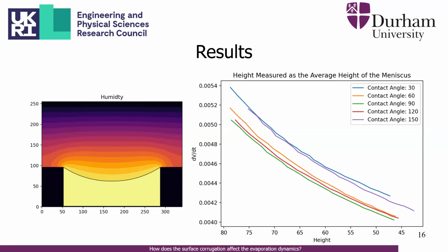So how do you define the location of the liquid gas interface? Because it's a diffuse interface, right? I'm a bit confused about how to do the interpolation. The distance is based on just assuming a tangent profile, for the halfway point at 0.5 in the profile. Because we have a diffuse interface, we can know the normal at any point to the interface, and then basically track that back, assuming a tangent profile.